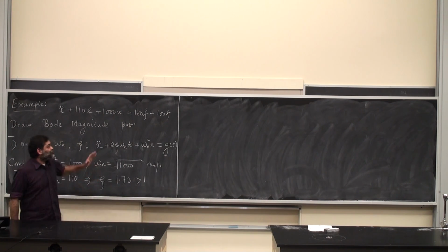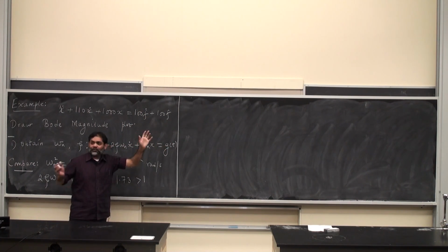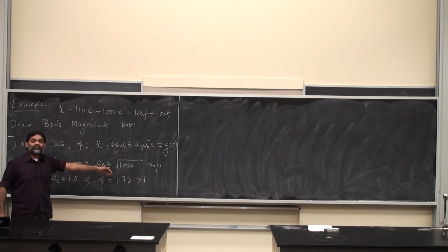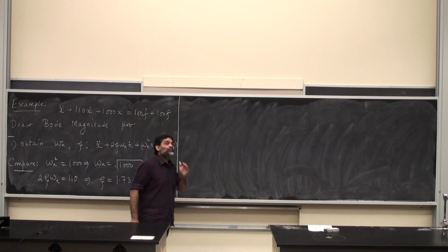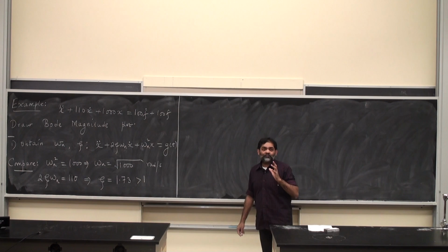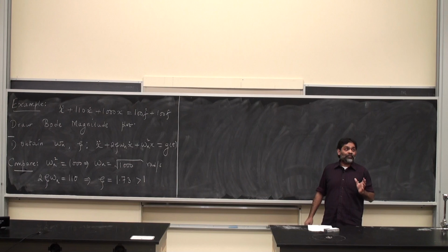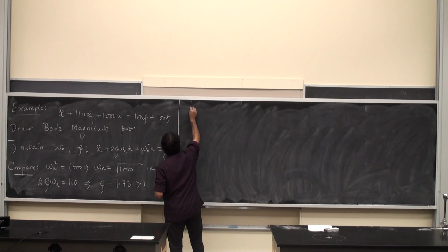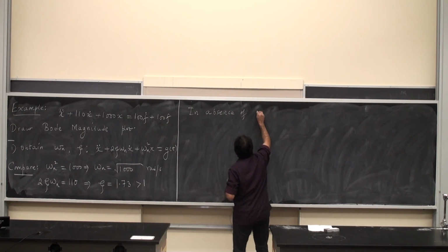Once again, if there were no numerator dynamics, if you club all these terms and call them some g of t, and given that the value of zeta is 1.73, the question I would ask myself is, will there be any physical peak for the magnitude of the system in the frequency response and the frequency domain? Obviously, we know that is not the case, because a physical peak is present in the absence of numerator dynamics